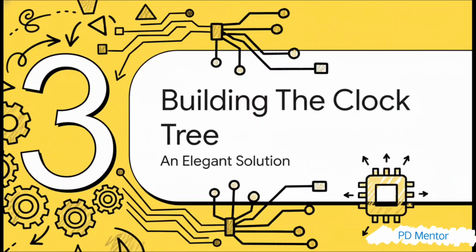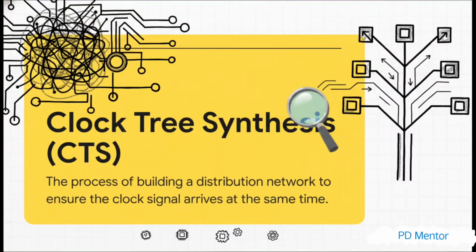Well, turns out they don't fight it. They get clever. They design around it with this really elegant solution called a clock tree. And the whole process is called clock tree synthesis, or CTS for short. Basically, it's the art of deliberately building out this delivery network, not as some tangled web, but as a perfectly structured network designed to make sure that arrival time difference is as close to zero as humanly possible.